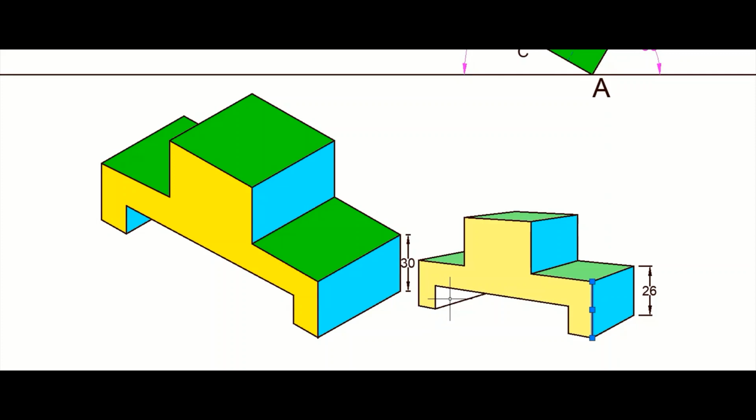All other edges in the perspective are away from the picture plane, so that is why they are shortened in their lengths. So that is the reasoning, and that is what adds some element of realism in perspective drawing, that something which is closer to us, this is the closest edge, is bigger as compared to any other edge which is relatively at a larger distance from the observer. So I hope you have learnt the steps that are required for making the 2-point perspective.